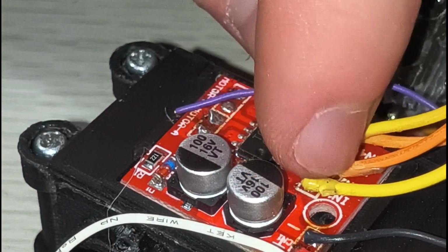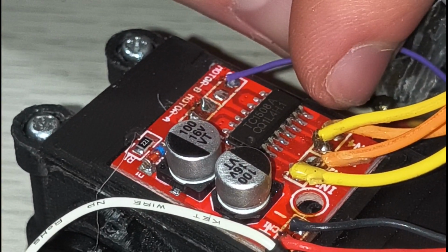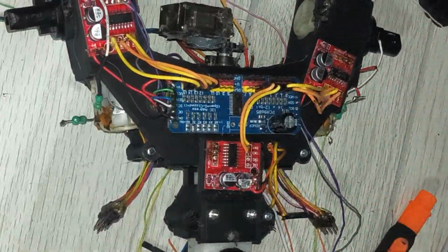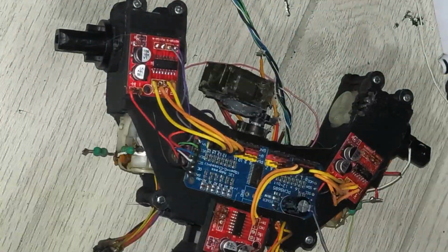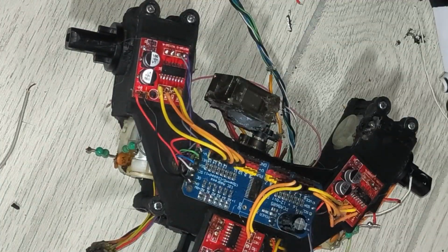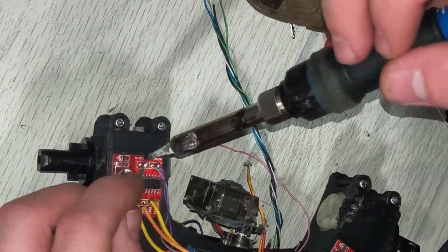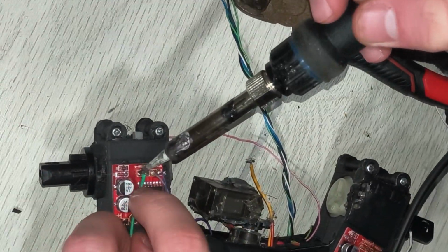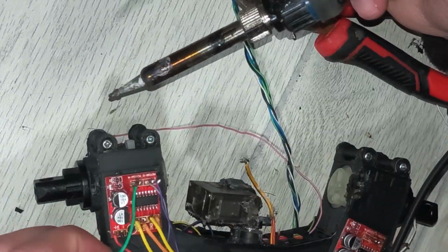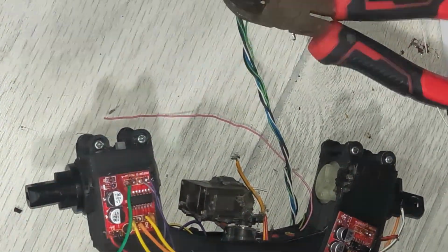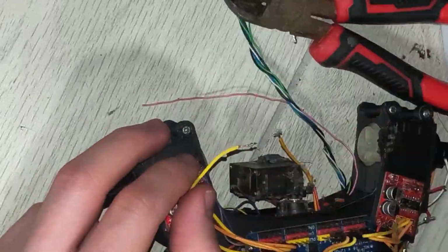So now it's time to wire up the motor controllers on the robot. Now you can see on the Robosapien motors, there's a resistor that's closer to the front plate and a resistor that's further away from the front plate. Now what you're going to do is take the one that is closer to the front plate and connect it to the left pad on the motor controller. And then you're going to take the resistor that's closer towards the back of the robot and connect that to the right pad on the motor controller. And you're going to do the exact same thing on the other side.